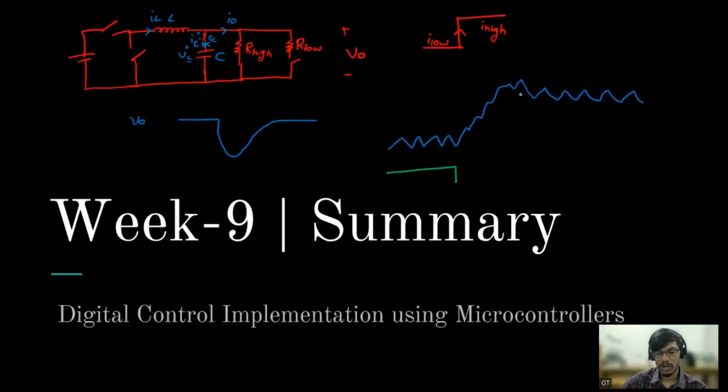The closed loop will ensure that the inductor will be ramped up so that again IL will be equal to this I high. The inductor has to supply; the capacitor will never supply, but as the inductor is not able to supply at that instant, the capacitor has provided. Now this voltage drop, whatever got discharged, will be charged again. Now the inductor will be slowly ramping up the current. Now the inductor current has increased and the voltage has also become V naught.